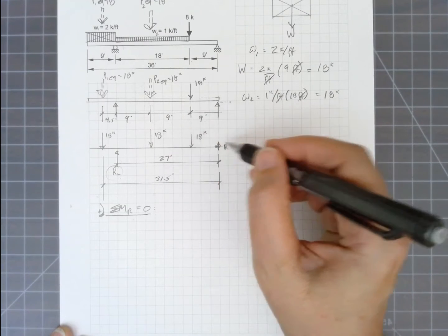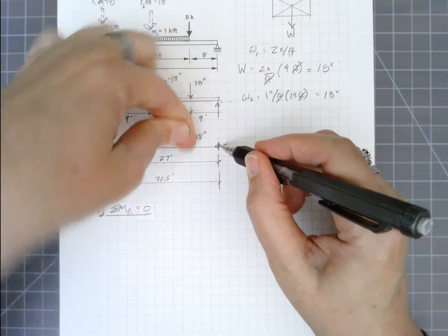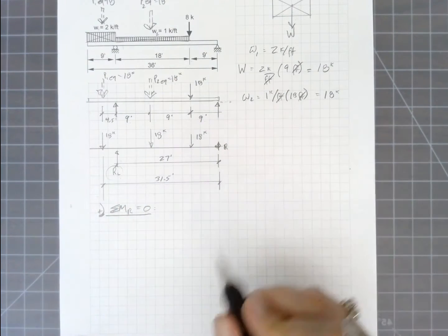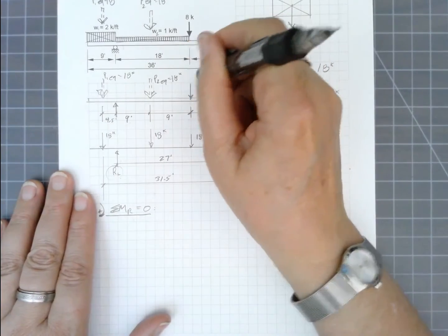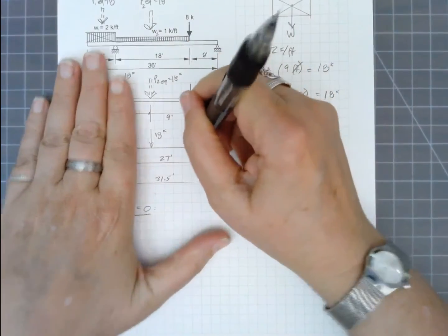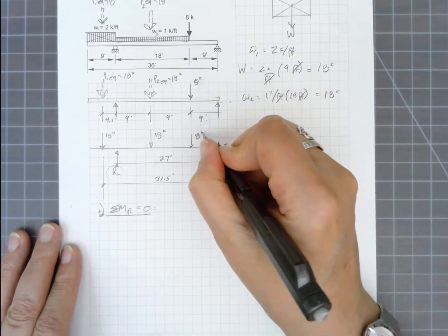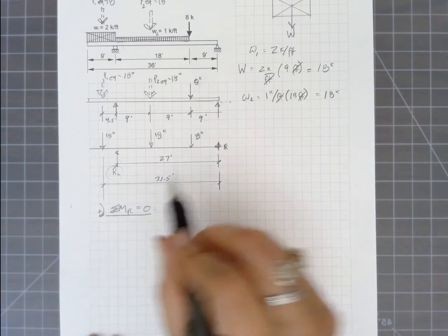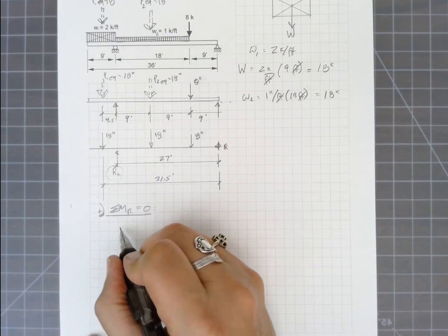So this 18 kips here would, if tethered to this point, want to rotate counterclockwise. In fact, that's true of all of these, so they're all negative 18 kips. I'm sorry, this is not 18. I wrote that wrong. That's 8 kips. So let's start from the left and work over to the right-hand side. I'll leave the reaction for the last term of the equation.